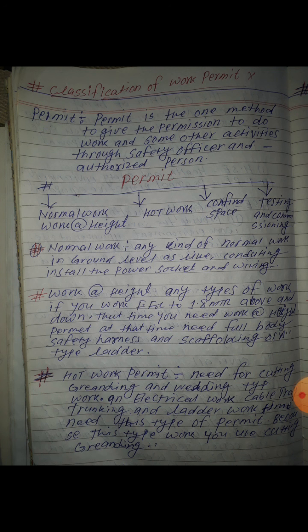Okay, don't go directly. You have the permit, so you think, okay, I am going and starting the work directly. Don't think like that. First check your working area, whether there are some hazards or not, and then you can allow the work. Okay, don't go directly inside the confined space before completing the safety check and removing hazards. Okay, so this means if the hazard is not clear, you cannot go inside. If all the hazards are controlled, then start the work.